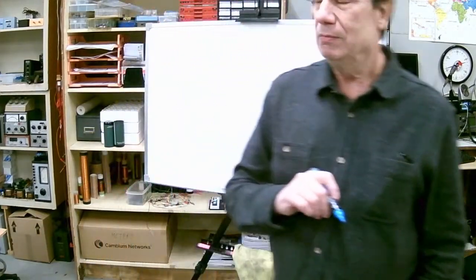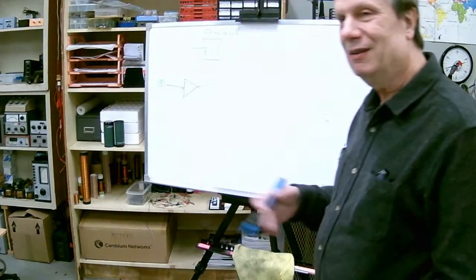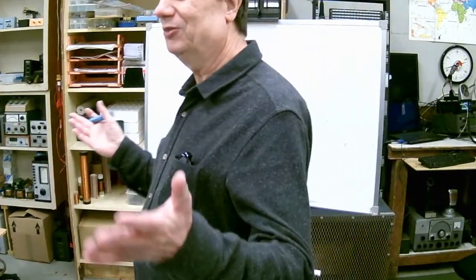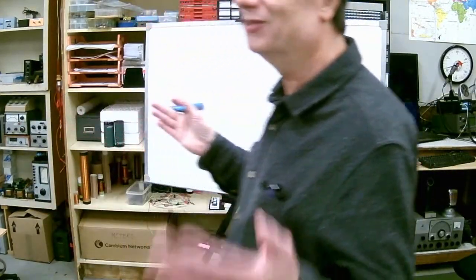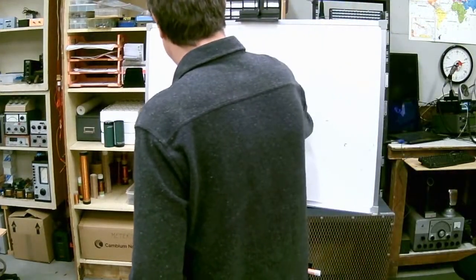We generally have an input impedance of 50 ohms, and we explained that 50 ohms became standardized for a lot of practical reasons, but basically it's in the ballpark of where an antenna is going to be at average height. We have a 50 ohm input signal here.